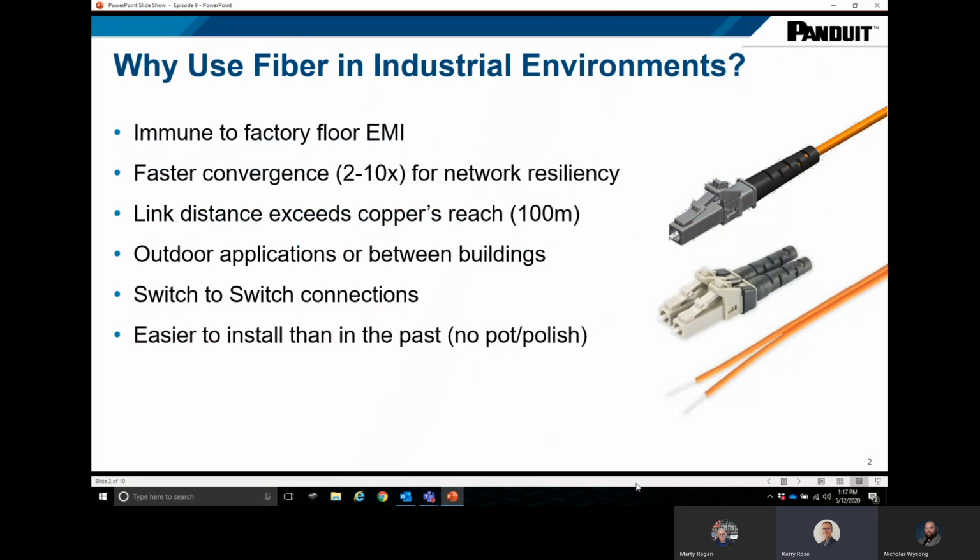In the past, we talked about fiber as a part of the structure of the cabling plant system. Well, there's some advantage to having fiber in your facility. First, the glass is not affected by noise, both EMI and RFI. If you need faster resiliency or recovery, fiber is an obvious choice, especially if you want to be under the 100 millisecond range in terms of, like, a REP ring recovery. Fiber optic cabling length distances exceed copper's cabling reach of 100 meters.